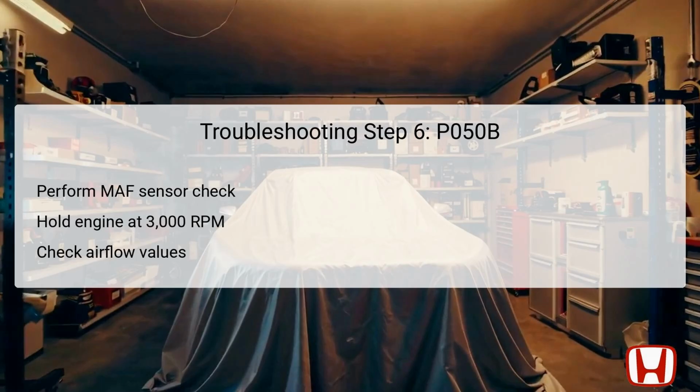Start by holding the engine speed steady at 3,000 RPM without any load, which allows the sensor to provide accurate readings while the engine is in a controlled environment. Continue this until the radiator fan engages, then allow the engine to return to idle. During this phase, you will need to hold the RPMs at 2,500 for 30 seconds and check the MAF sensor's